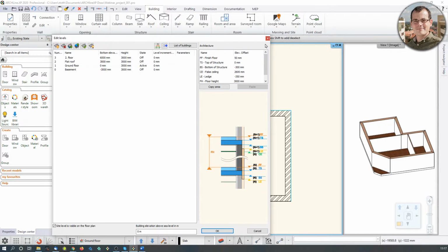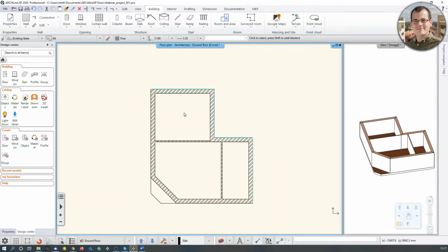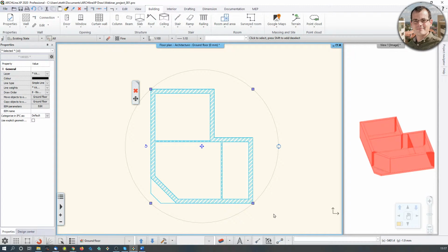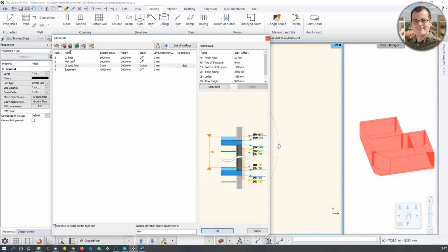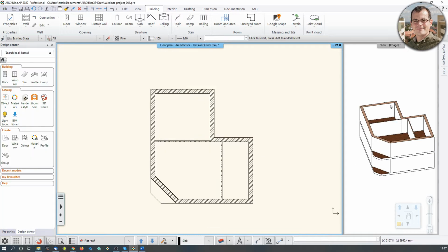And I want to sort of have another floor above this one, and that is going to be just a flat roof, maybe with some walls around it, so we are not going to fall off. So what do? The easiest way is to select the whole drawing and copy it 1 floor up. And we do that by selecting the whole thing and going to ground floor and clicking on this element over here, copy objects to other floor, and select where you want to copy these things to. Okay, and now you have 2 floors on top of each other.